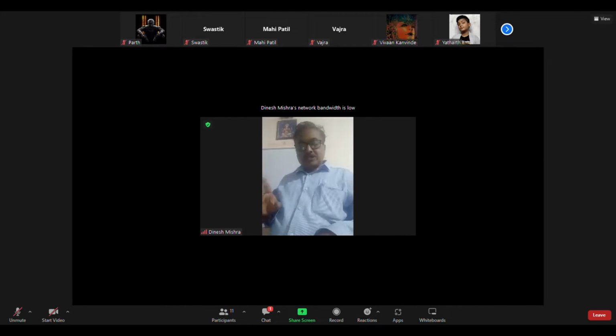Now we see what the deflecting system is. There is a coil. If you pass current in that coil, magnetic force will be produced, and that coil is connected to a spindle. When the spindle moves, the pointer will move, and the pointer will show the amount of current by giving the reading. This is the basic system of the meter.